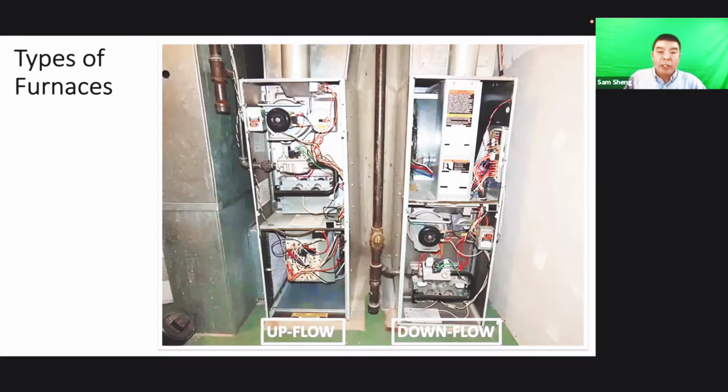All that should be in the manufacturer's manual. Oh, sorry, the manual. Yeah. So if you install a different orientation, like from upflow, you should read the manual to know how to change the inducer motor direction. So don't cause trouble for the condensate.